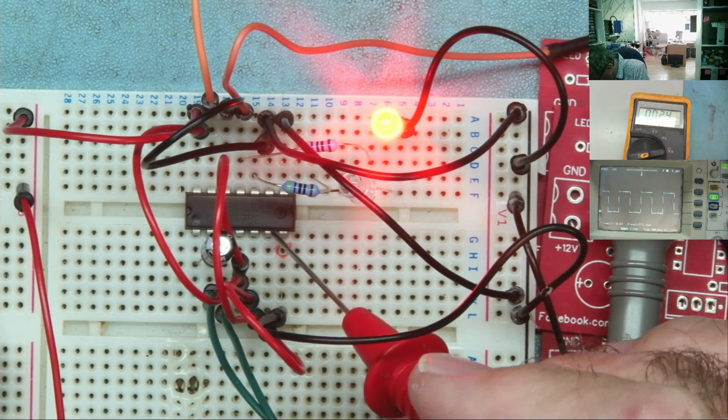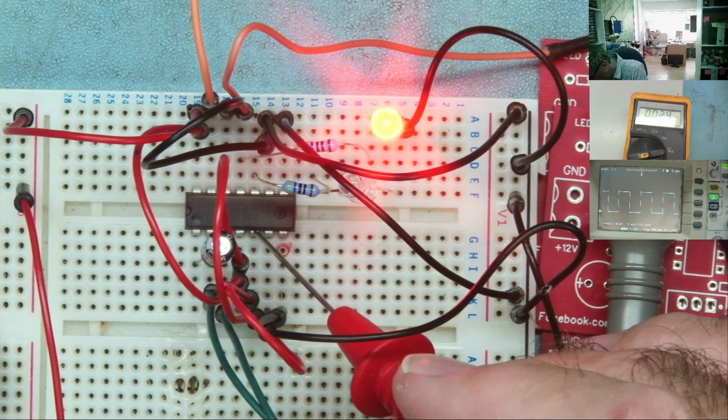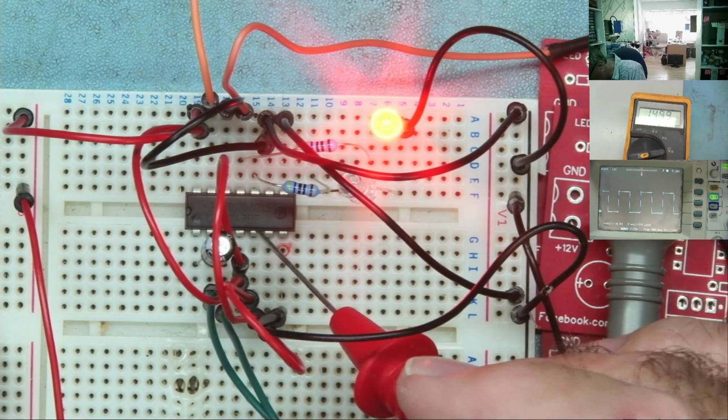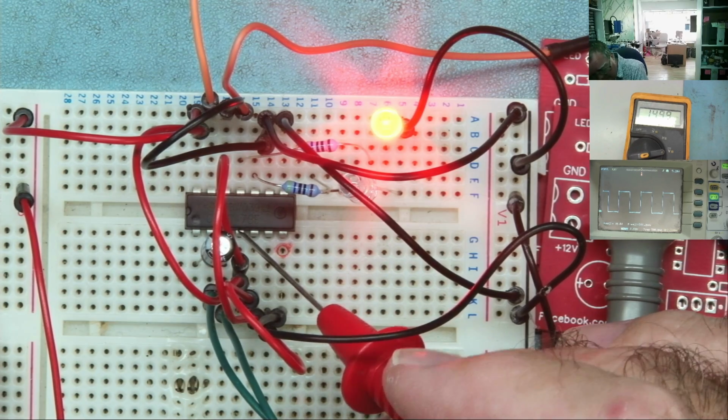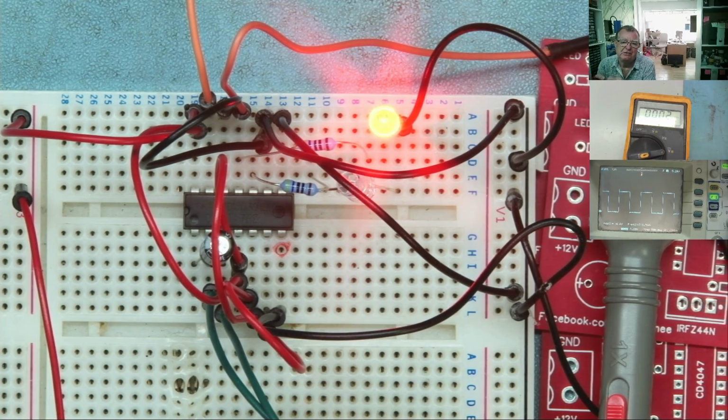So this is 6, 15 volts, 5 is 15 volts, 4 is 15 volts. And then VSS, voltage to the sources. This is your negative supply or ground in this single supply rail circuit. You'll see VEE, maybe, that's voltage to emitters. You don't really see that one particularly often, but VSS you do see.